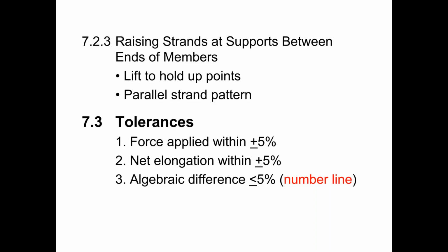That hardware can be used multiple times. So we want to be careful that we properly inspect our hold-up locations after each use. Make sure that the elevation is correct and that the hardware is in good working order. Since it is exposed to the elements, if it's an outside bed, the hold-up hardware can corrode over time.